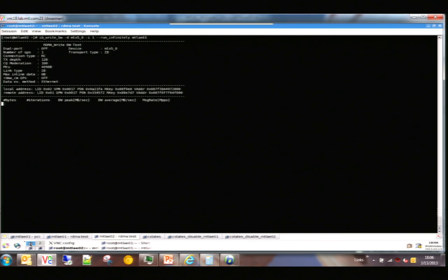And what we see here is around 51 gigabits, converting the megabytes per second to gigabits per second. We get around 51 gigabits per second on a Gen 3 server. I told you the limitation is around 52 to 54, so I owe you 1 gigabit more, and we'll see how we reach that with further tuning. So I have some scripts here that retrain the link to a lower speed. So I'm going to degrade the link, the Gen 3 link, to Gen 2.